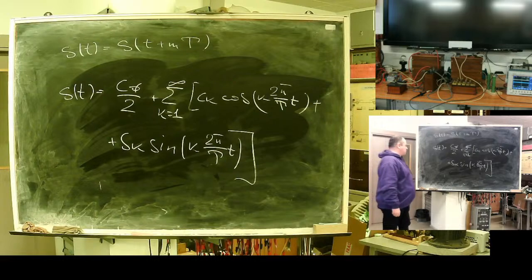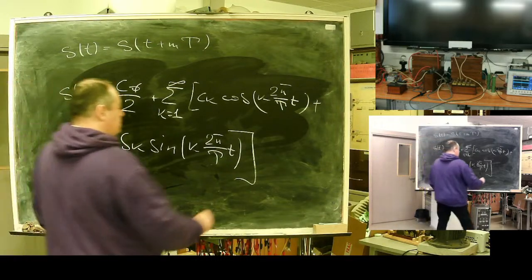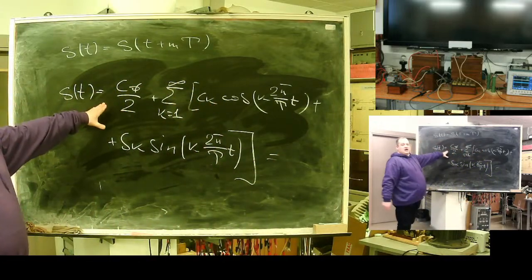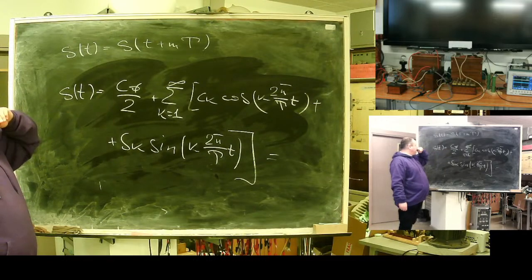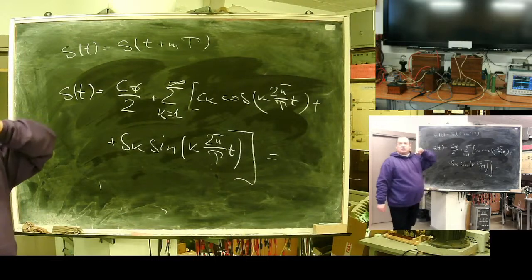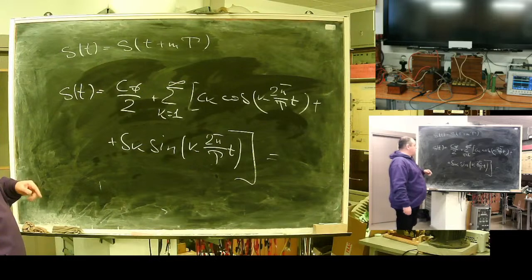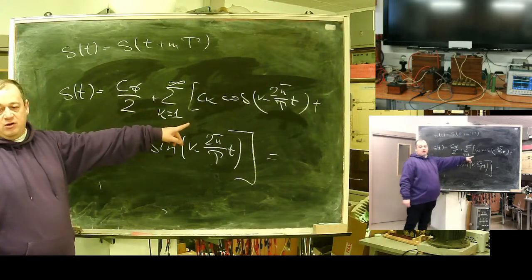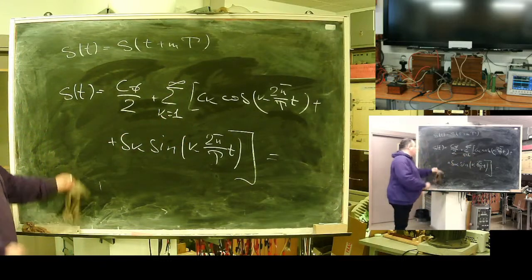I can rewrite it in a bit more compact form, but this is the key idea. Any complex voltage, current, anything, but periodic, it should repeat itself, can be substituted with a DC component and a set of ideal AC components.